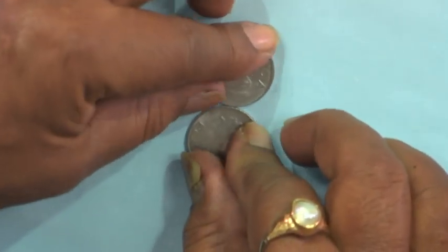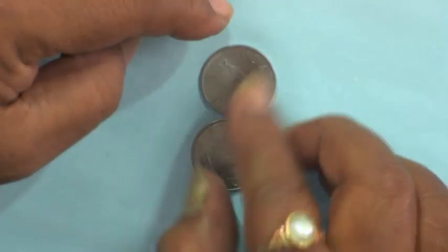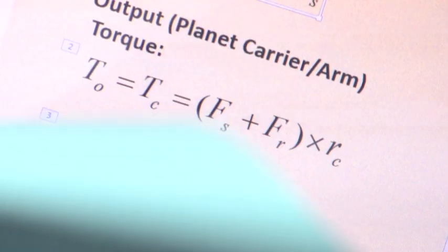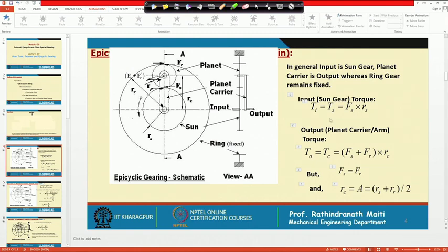If we rotate at a fixed axis, you will find this will be 1:1. This means that by allowing the touching gear to rotate about its own axis and revolve around the other axis of the fixed gear, we will gain some motion, that is the epicyclic motion, that is the planetary gear motion.